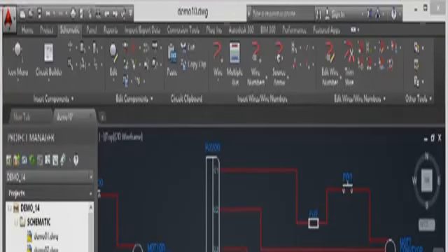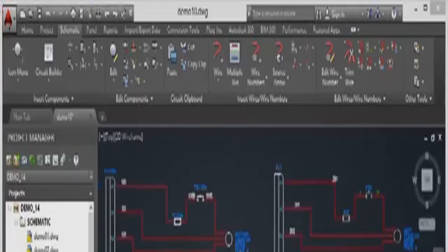The nice thing about using these W-block circuits is once you've inserted one into your AutoCAD electrical drawing, it's very, very easy to re-tag it and make sure that everything is neat and tidy, because it inserts as a circuit with all its wires, connectors and components in place. So we're still in the Demo 14 project and we're still using Drawing Demo 10. What I've done here by way of a comparison is the circuit on the left is all neatly tidied up and ready to be used in the AutoCAD electrical drawing.